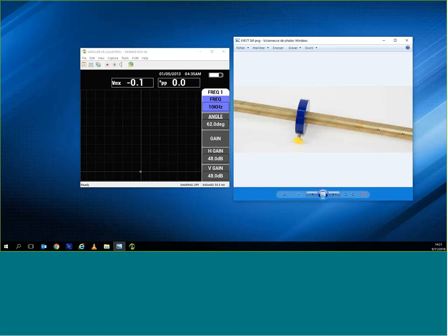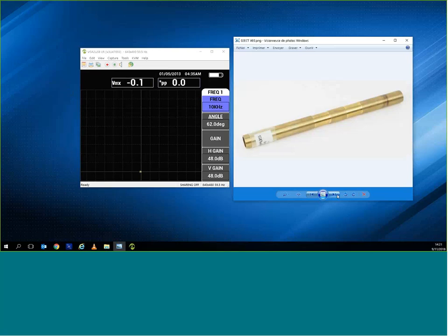so I'll show you the picture of the support of the calibration tube. Pardon me. There we go. So what we have here is we have 2 OD grooves and we have an ID groove right here. So what we did is we've calibrated the largest groove. It's about 80% of the screen height. The next one's about 40, so it's about 2 up, and then we have the ID, which is over here. So what we did was we just set up the signal to say, well, look, I'm looking for anything that's over 80, which should be 8 vertical bars up.